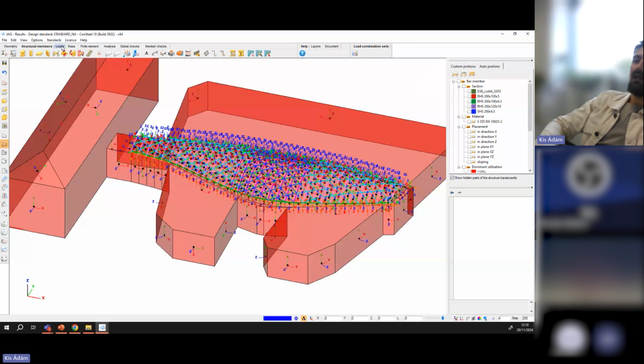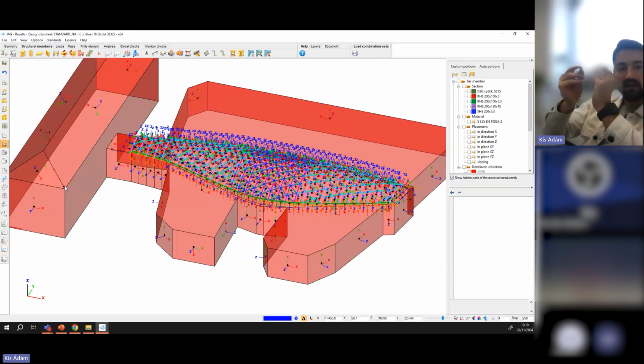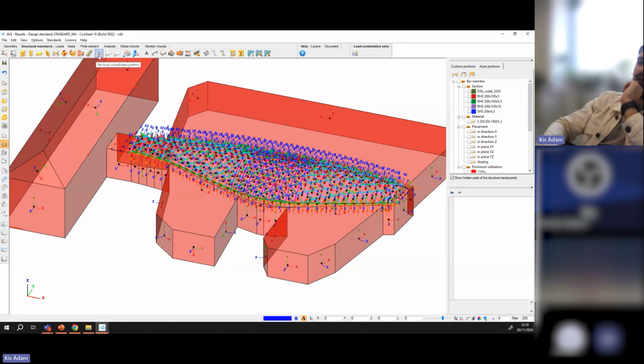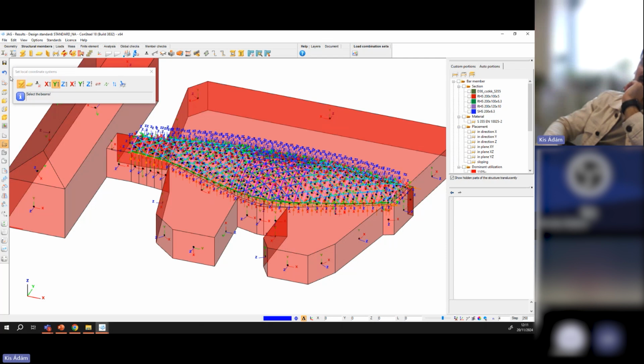When you are running simulations, we have a few checks regarding whether the building is sealed, because we are verifying that the building is sealed, meaning that the corner vertices are connected and the building is closed. However, you have to ensure that the directions of these local coordinates are adequate for load creation, which you can do by setting the local coordinate system.